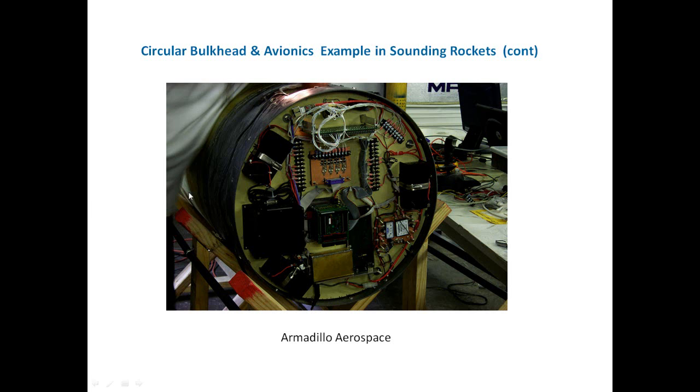So one of our tasks might be to predict what the response of this bulkhead is going to be under various types of base excitations. Then from that we would take the acceleration response of the plate, and that acceleration response becomes the base input for these different boxes and components. Then we would take those boxes and components and mount them to a shaker table and do testing.